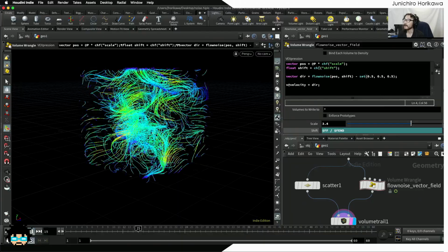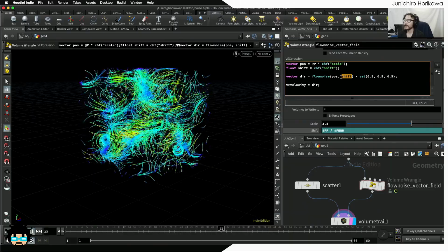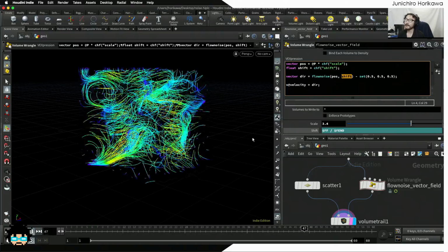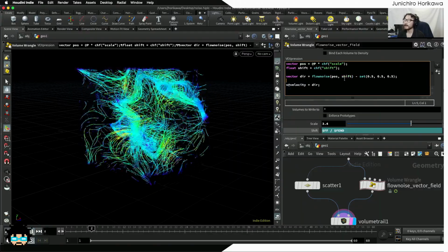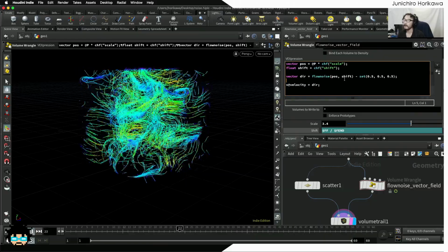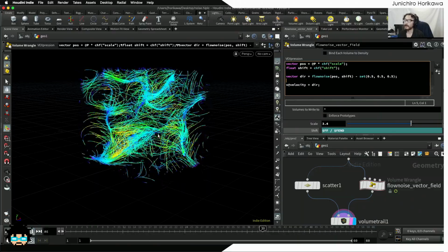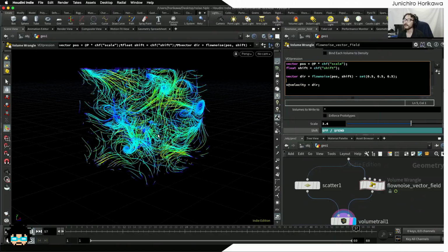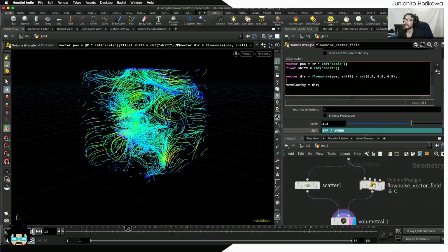That is because I'm using this flow noise for the shift, which is in between 0 to 1 as a periodic size. Okay, you can do the same thing with the P noise as well by setting the shift, the fourth coordinate, to 1 and all the other coordinates, x, y, z tiling size, to 0, which will create the same effect as this one. But if you just want to make the last parameter or last coordinate periodic, then using flow noise might make more sense, which is easier to use.